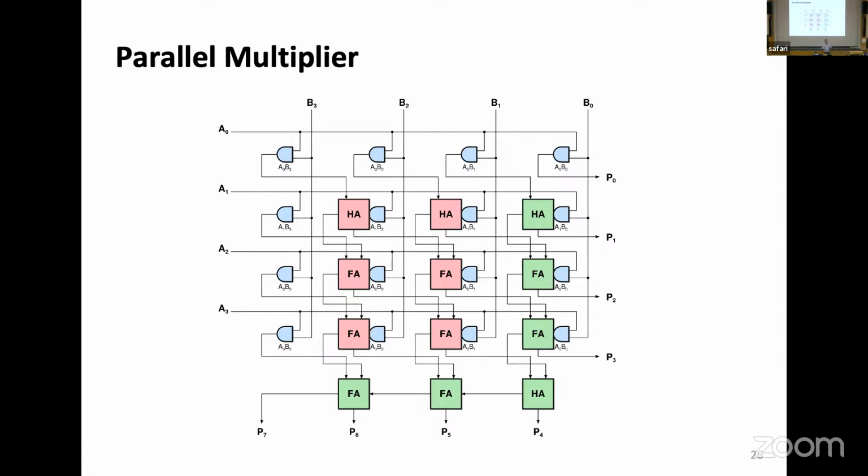If you're making a tiny, tiny microcontroller that has to fit into your ear or in your lungs or something like that, maybe you don't have the power, the size, the area to put it. Maybe you don't do multiplication so often. So why do I have to put hardware for multiplication into my processor? It happens once every blue moon. If that happens, you say, I have a software routine. Yes?